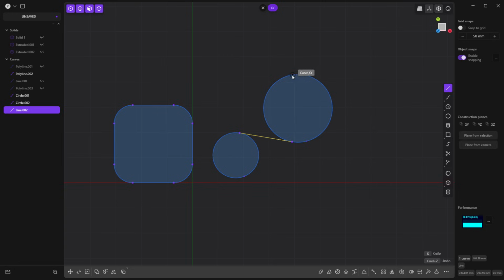Now if I come up here and just pick a random point, there will be a position where I have tangency with that curve. You can see the pink projected line. And if I move this around, that's going to go away and it'll snap back until it's horizontal or perpendicular to Y in this case. So there are those positions that you'll just find when you're creating these curves. I'm going to go ahead and snap here, and then I'm going to come down and find tangency on this, right click to accept. So now this line here is tangent to both of these circles.